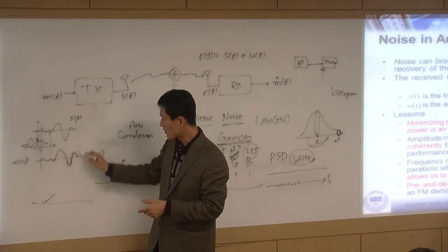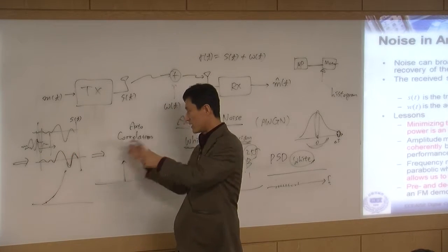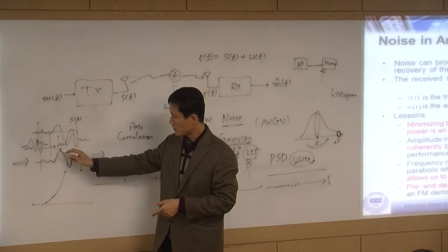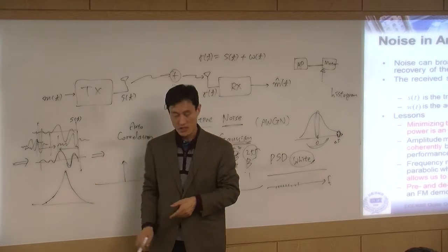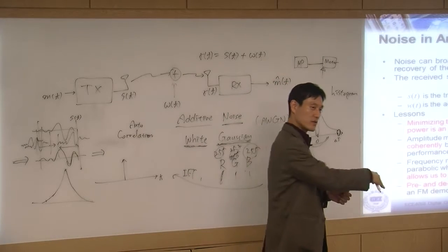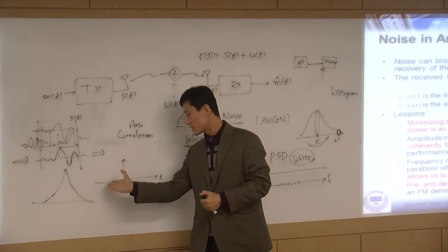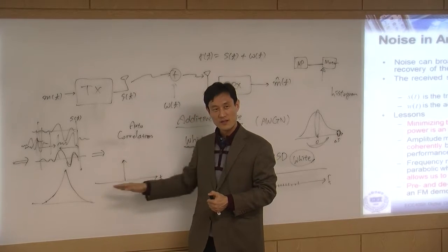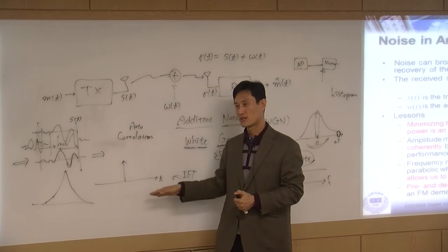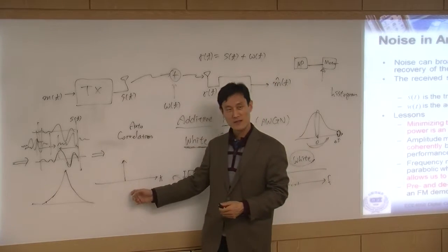If you have a perfect overlap, you get the maximum value. When you keep sliding and move out, again you have a little overlap, so it goes down again. Typically, the autocorrelation function is like this, going up, going down. But in this case, there's nothing like going up or going down. It's zero always, suddenly it jumps, and then again back to zero. So that's a very special kind of autocorrelation. What does that mean?